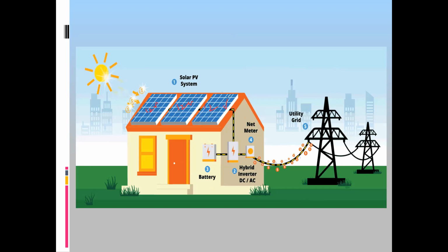But if the weather is cloudy, then what will happen? The amount will decrease. Now it will provide 6. So the voltage output will decrease. So we cannot directly connect them to a device. First we have to store the energy in a battery, and from the battery we will utilize it, so we get a constant energy. Is the concept of solar panels clear, how we can use it to generate electricity?